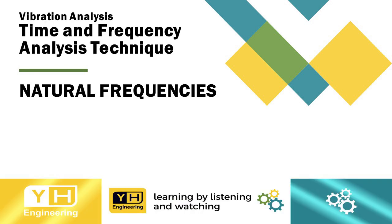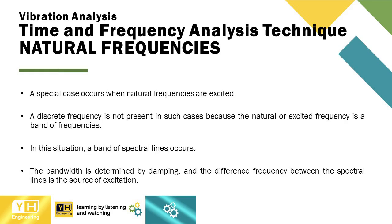Vibration analysis. Time and frequency analysis technique. Natural frequencies. A special case occurs when natural frequencies are excited. A discrete frequency is not present in such cases because the natural or excited frequency is a band of frequencies. In this situation, a band of spectral lines occurs. The bandwidth is determined by damping, and the difference frequency between the spectral lines is the source of excitation.